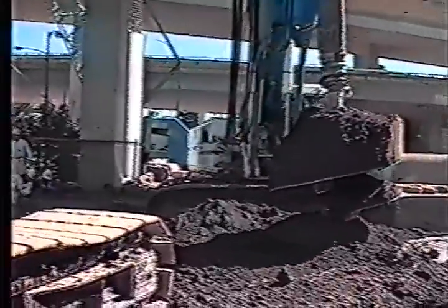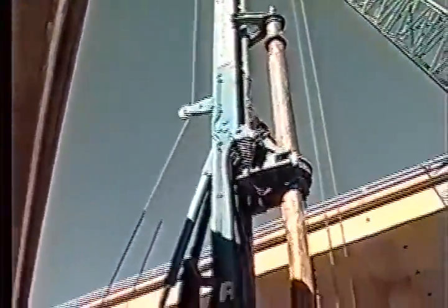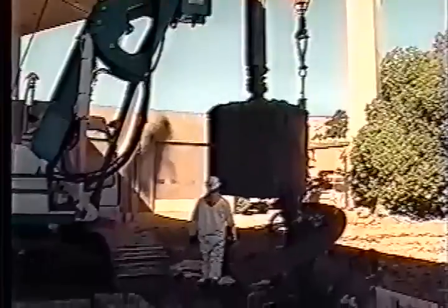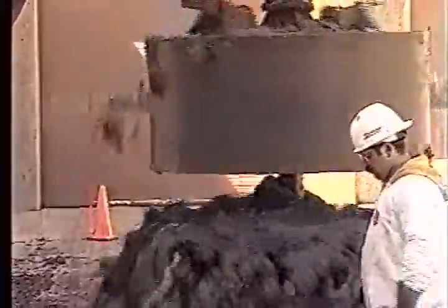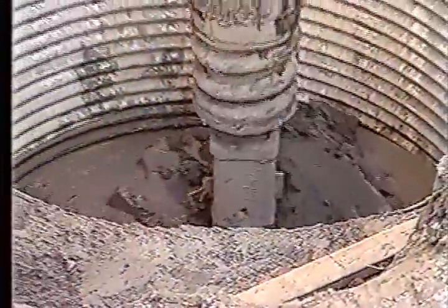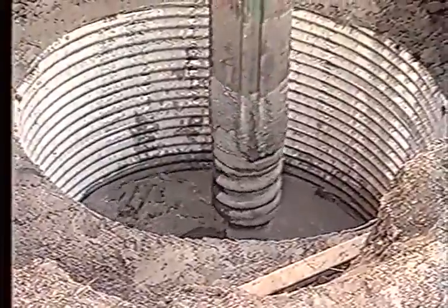Throughout the world, drilled shafts are used as deep foundations to support large axial loads from high-rise buildings, bridges, and other up-reaching structures. Drilled shafts are commonly constructed by employing rotary drilling equipment to drill a cylindrical hole. This hole may remain open in soils with cohesion or rock. When caving soils are encountered, the hole may be kept open by using drilling slurry or casings.